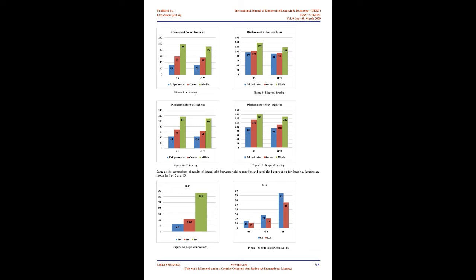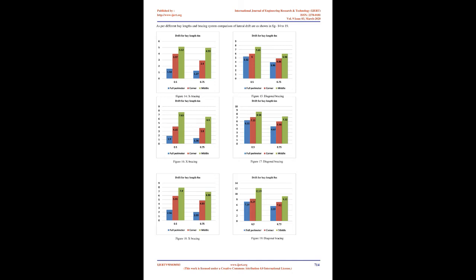As per past experiences and researches, the most favorable results are obtained for the range of 0.5 to 0.7 fixity factor. The present study incorporates the analysis of steel frame structure using fixity factors 0.5 and 0.75, i.e. 50% partial release structure and 25% partial release in structure. In the end fixity factor, Ri is the rotational spring stiffness of connections, and EI/L is the flexural stiffness of elements.